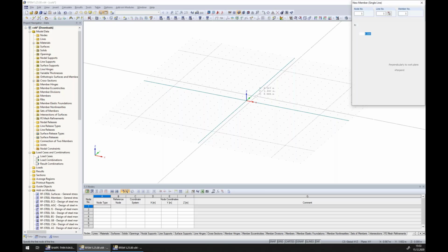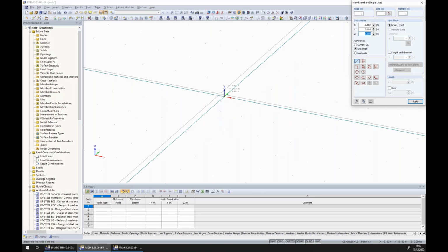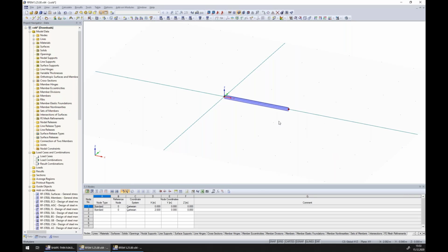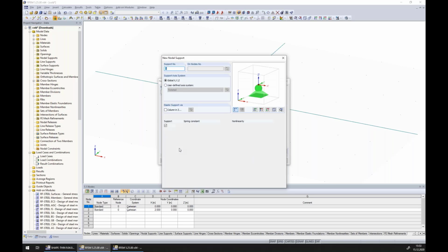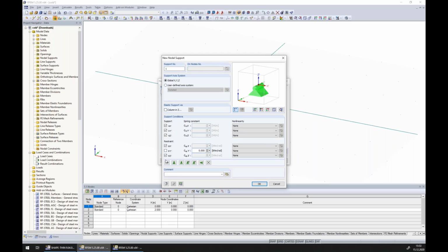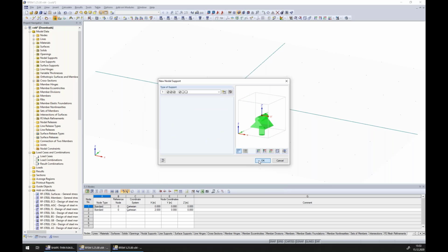now we can place the member in this space. To reach this defined bending moment, I need a 2-meter long beam supported on two supports, right and left. To prevent rotation about our axis, I support here the x axis.